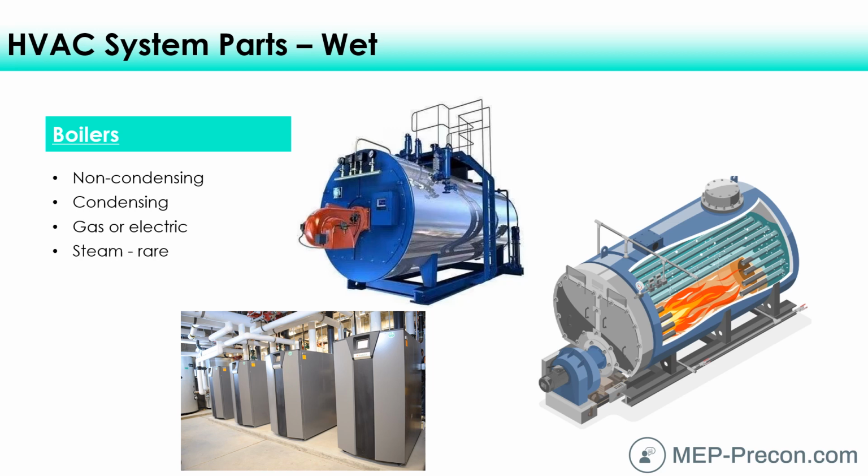And we talked about hydronic pipe, or hydronic, meaning water. You could have steam boilers too. Steam is getting pretty rare. You typically only see it in systems that are used for some process, maybe for hospitals, for autoclaves to clean their devices, maybe for humidifiers in areas of the country where the energy code would allow steam humidification for the air. But they're usually not used for general HVAC heating anymore.